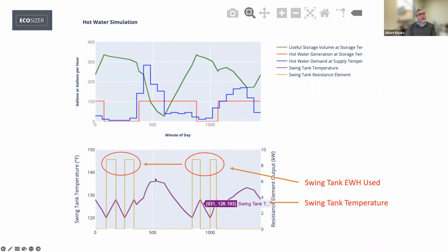If people are still there consuming water, the heat pumps could be on and it's trying to recover itself, but the load is outstripping the recovery, right? So we don't really see it. We might see it where that precipitous angle starts drifting off right where it hits that red line. So we've got some recovery going on, the load's softening a little bit, and the tank doesn't deplete as fast. But as soon as that load's really gone, the tank temperature starts hiking uphill again.